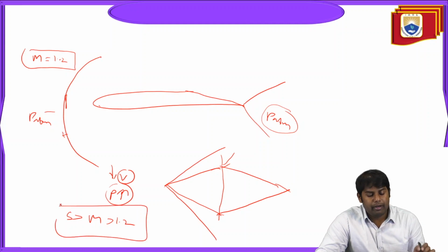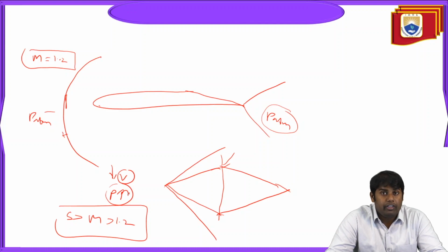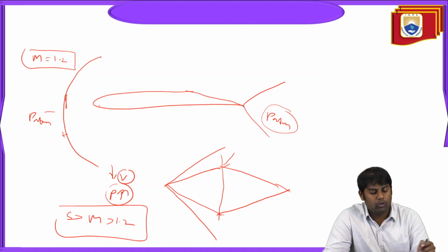Now when the Mach number is increasing greater than 5, what happens actually? What type of CFD do we need to see? When the Mach number is greater than 5, you have the molecular effects. The bond between the molecules breaks. The oxygen atoms and the nitrogen atoms break their bond. Why? Because I think we know the boundary layer.